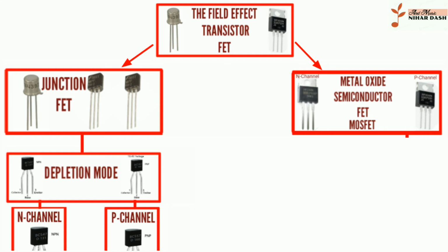The field effect transistor is a three-terminal device that is constructed with no PN junctions within the main current carrying path between the drain and the source terminals. These terminals correspond in function to the collector and the emitter respectively of the bipolar transistor. The current path between these two terminals is called a channel, which may be made of either a P-type or an N-type semiconductor material. The control of current flowing in this channel is achieved by varying the voltage applied to the gate.